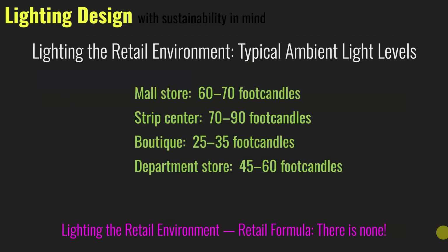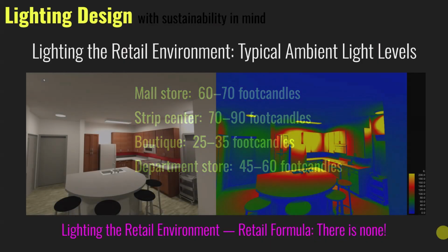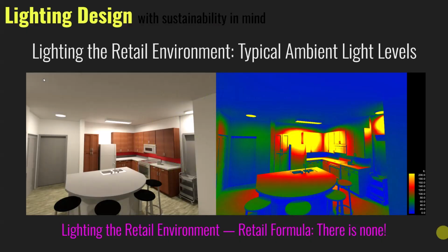General light levels from IES, the Illuminating Engineers Society, which is very important. You definitely want to know the recommended foot candle levels, the brightness that you should be designing for. AGI 32 is the lighting design software that does that. And I'm sure Revit does some of this, where you take into consideration the quality of the finishes, smooth, glossy, reflective, matte, textured, as well as the colors.